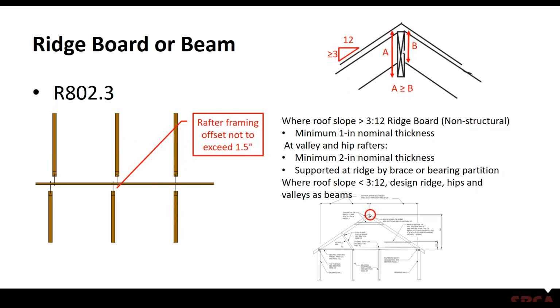What you're doing with true rafter framing is field building a truss. So the ridge board is not there to support a gravity load applied to the rafters. It's basically there to provide something that the rafters can push against.